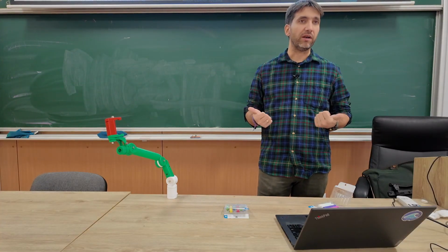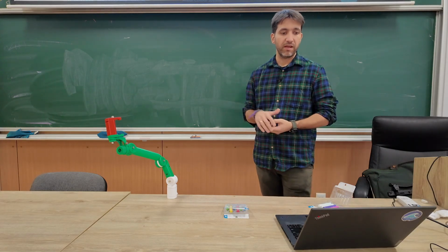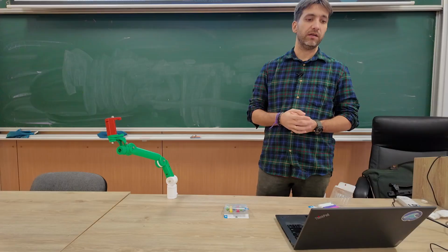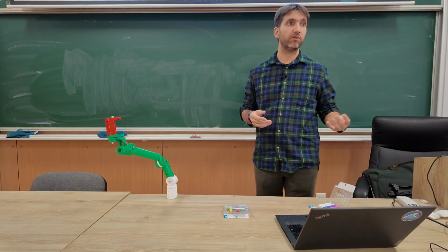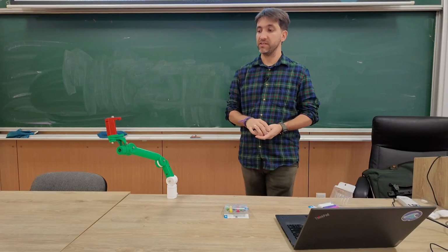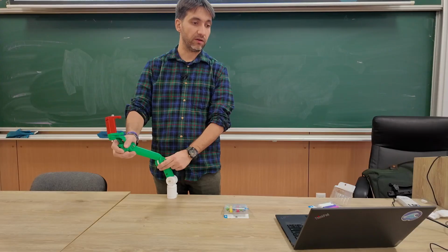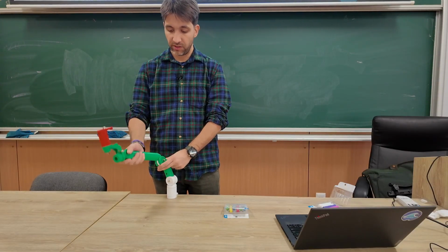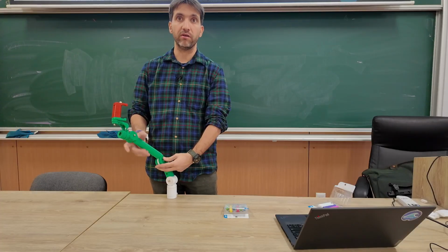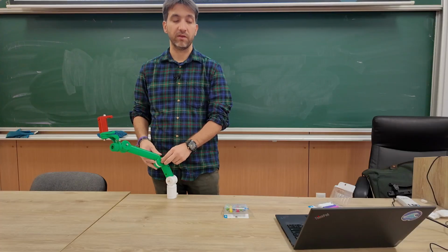The point is more than one, right? So using a PID, can I have multiple errors, multiple inputs, multiple set points, and multiple references? Because if I control the joints and I read the joint coordinates, I need a controller controlling all of them, not just one of them.